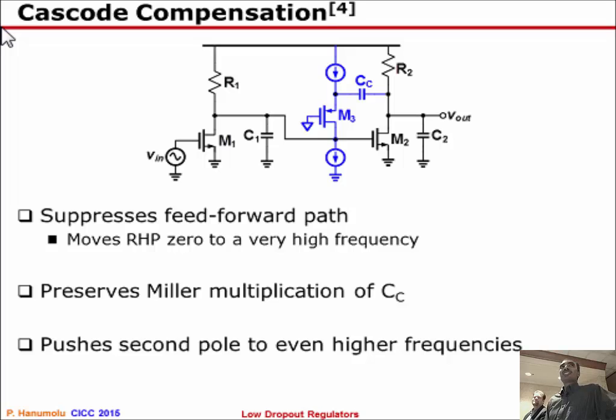I think if you pigeonhole me by saying I want good rejection and no load operation, then that's a difficult problem. But if you give some room for somewhat degraded power supply rejection, some of these resistive based digital LDOs, where they are just physically changing the resistance, they have no rejection.